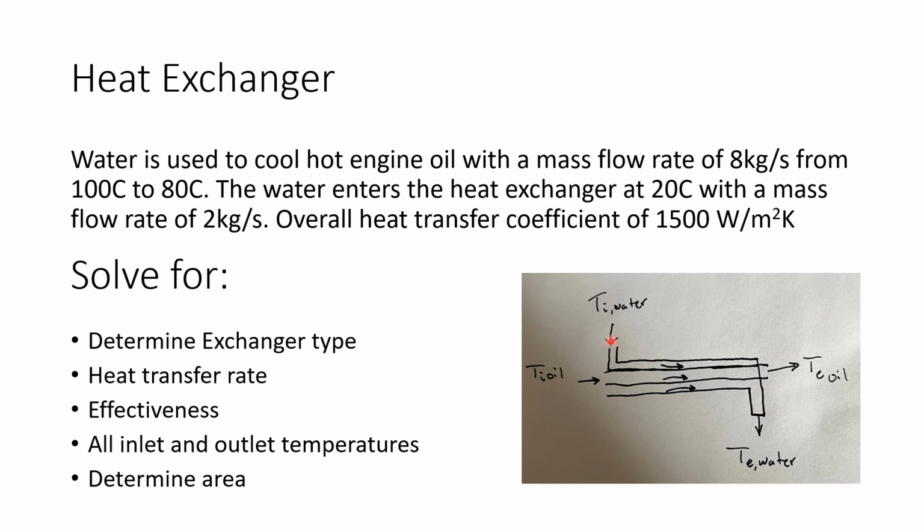This image here in the bottom right hand corner was a rough drawing of the parallel heat exchanger that I chose to analyze. You can see here water's coming in from the top and traveling parallel with the oil, and then exiting here, and then the oil is entering here, traveling along this pipe or tube, and then exiting on this side. That's why it's called parallel, because they're both flowing in the same direction.